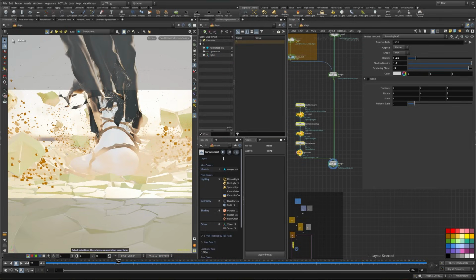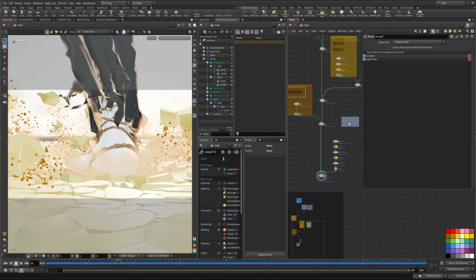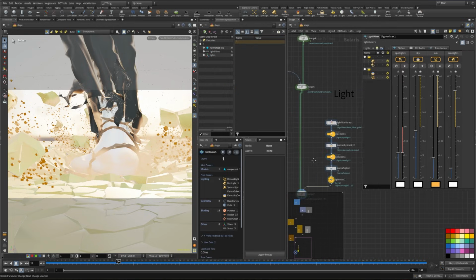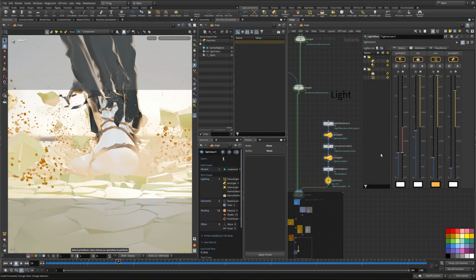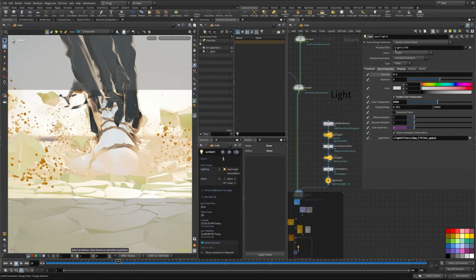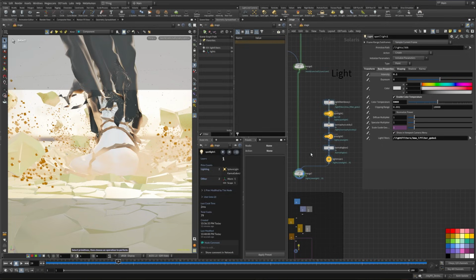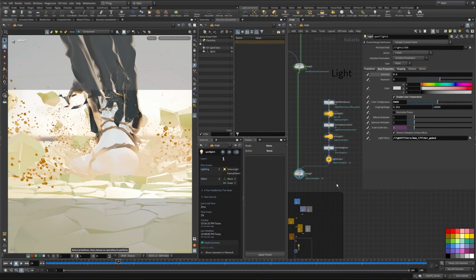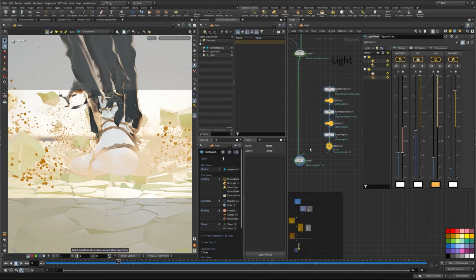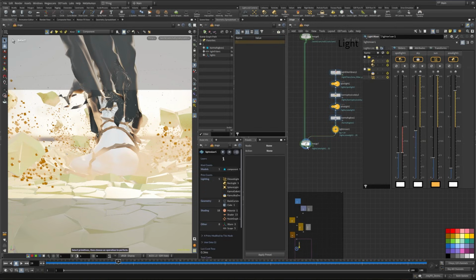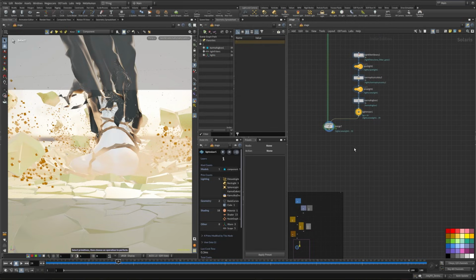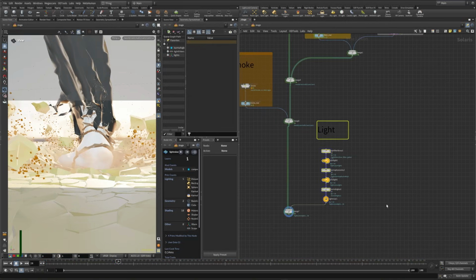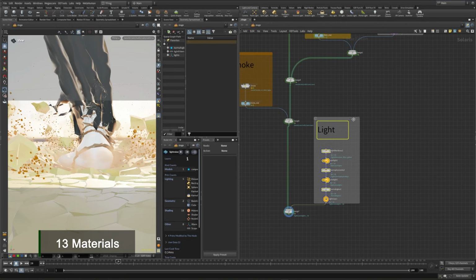And let's select everything, and let's grab the smoke from here. We call it light. And one problem with the light mixer here is if we would change the path here to, for example, /world, lights and $s, the light mixer would reset because it's bound to the prim path. And sometimes I'm not really a fan of the light mixer because of this. So make sure you always just place it at the end. I made the mistake here for now, but yeah, so you know for the future. All right, we can move on now after recreating this box here for the lighting.